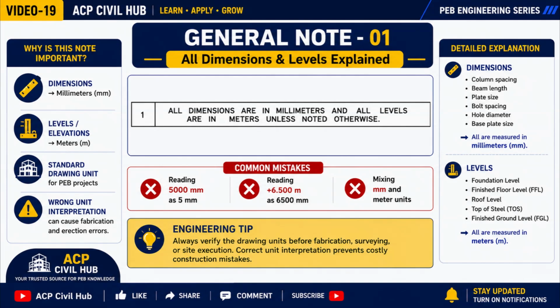This is the first general note of the drawing, and it is one of the most important notes that every engineer, detailer, fabricator, and site engineer must understand before using any drawing. The note clearly states, all dimensions are in millimeters and all levels are in meters unless noted otherwise. This means that every length, width, spacing, plate size, bolt distance, and structural dimension shown in the drawing must be read in millimeters. For example, if a dimension is written as 5,000, it means 5,000 millimeters, not 5 millimeters.